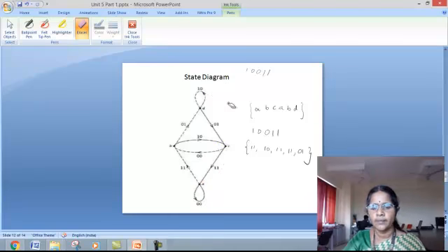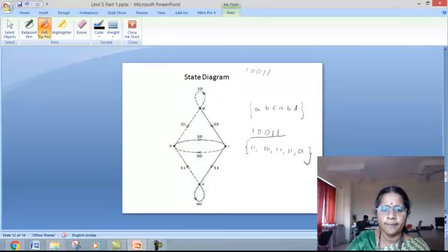having drawn the state diagram, how to encode the message sequence. Take the same message sequence which is already considered, 10011. Now start with the all zeros state. So you are here now. Presently the message bit is 1. So follow the state when the input is 1. So here when it is in state A and when the input is 1, it goes to next state B and the output produced is 1 1.